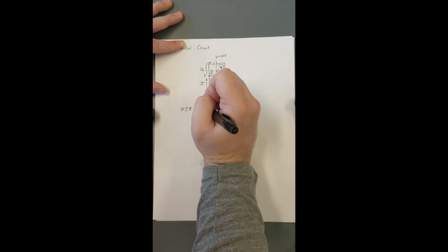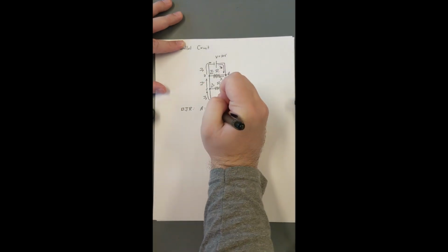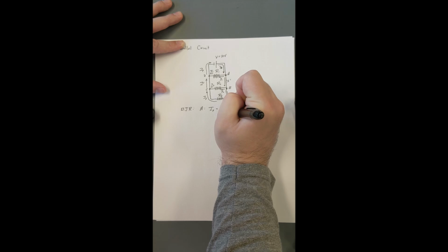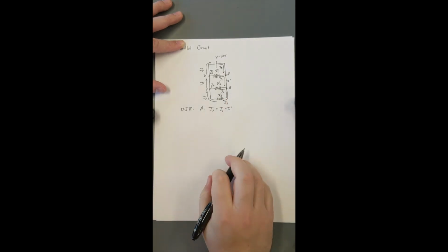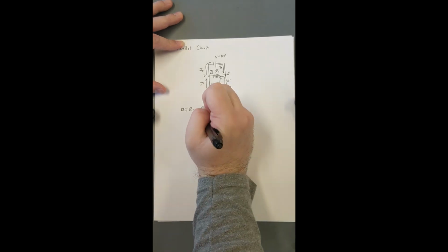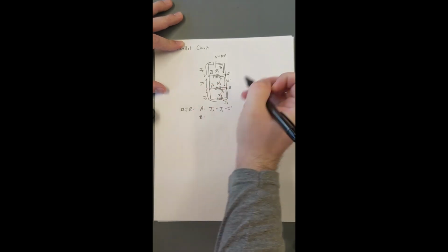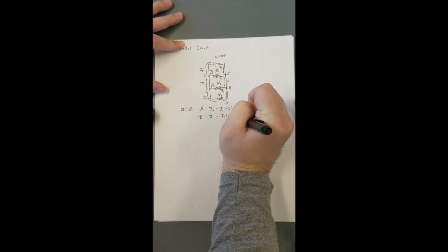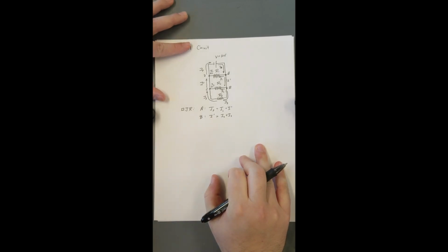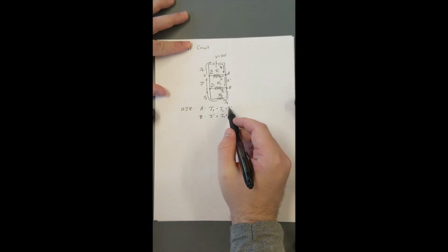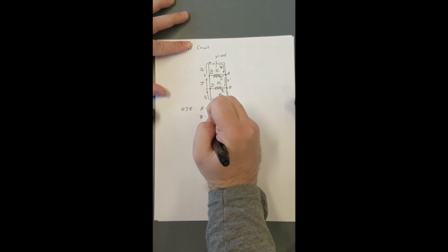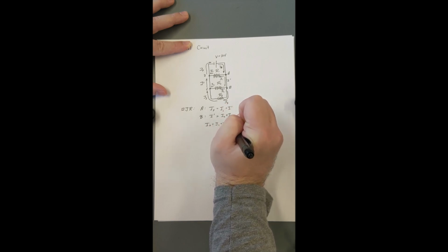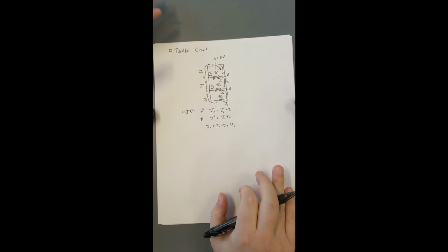All right, so let's look at A. At A, we have I sub P, and I sub P is splitting off into I sub 1 and I prime. So that's our first junction. Our second junction, B, gives us I prime equaling I2 plus I3. I prime is common between these two equations, so if we rewrite this, we can write I sub P just equals I sub 1 plus I sub 2 plus I sub 3, and just neglect I prime here.